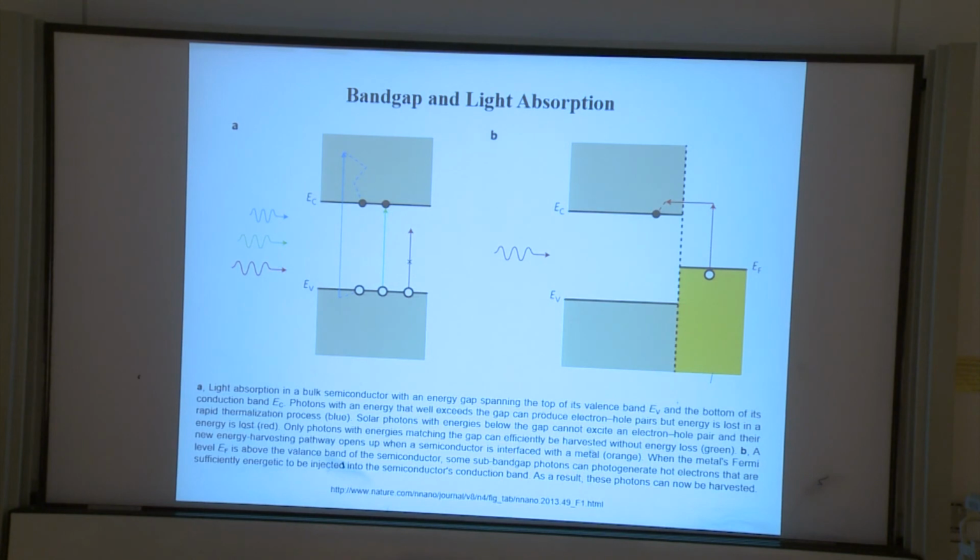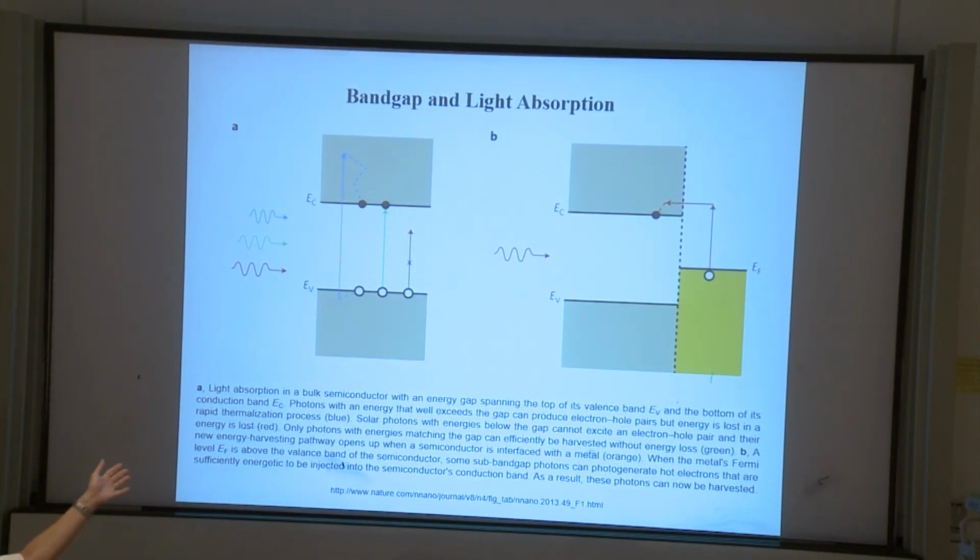So from this perspective, the red light is transparent to the material, or the material is transparent to this kind of light. For example, if we are using glass, you can see through the glass. That means visible light cannot excite the electrons in the glass from the valence band to the conduction band. However, the glass can be UV protective.